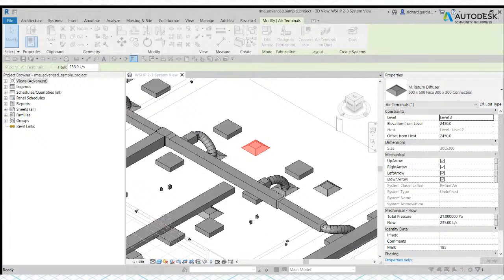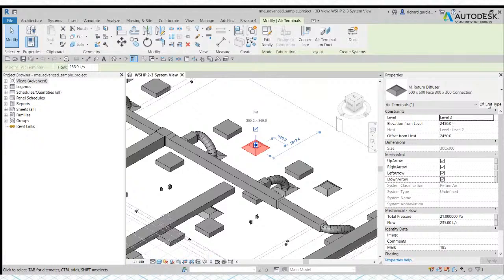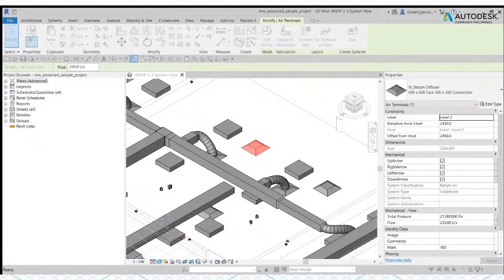So if I change the width, let's say to 300, for example, and I have 100 inserted in this project with this type, all of them will change the width to 300. So that's why it's not a good idea to simply go to your type properties and then straight away change the property here. Don't do that if you're not sure of what you are doing.